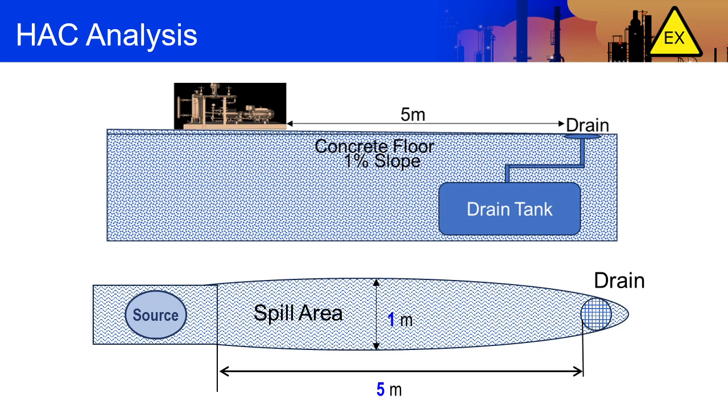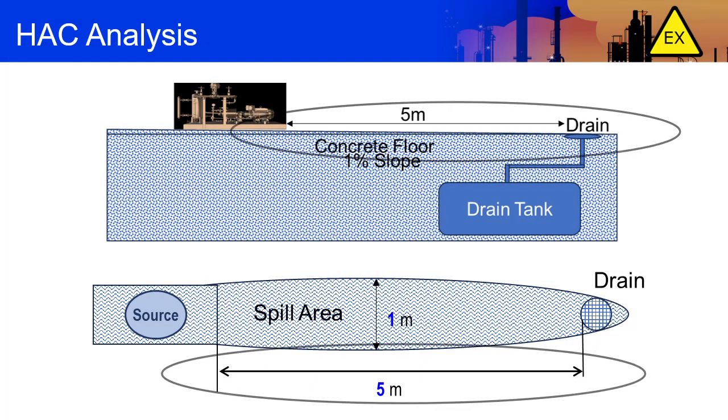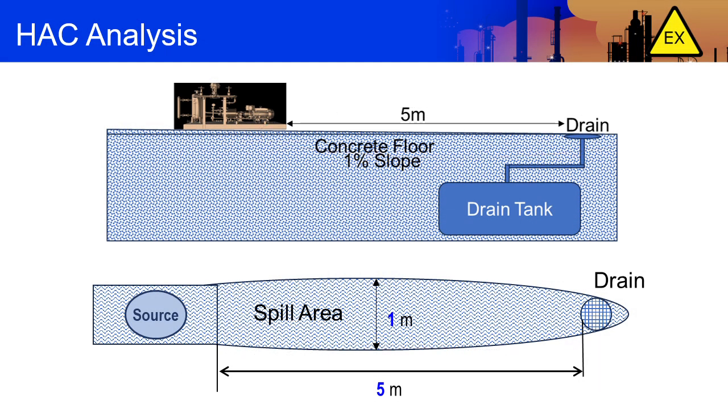Given that this application does not incorporate spill containment, we will have to make some assumptions related to the size of the pool release. This will be a function of how much fluid we expect to release under normal operation, the permeability and the slope of the surface the spill will collect on, how close the equipment is to a drain system, and how often the equipment is physically monitored by operations.